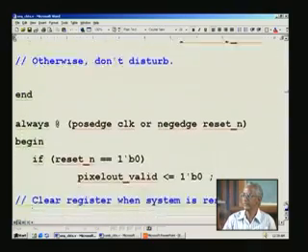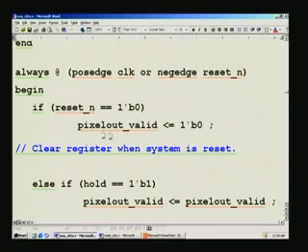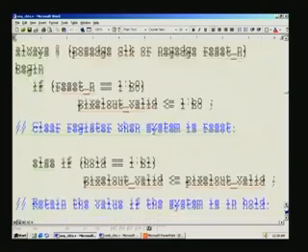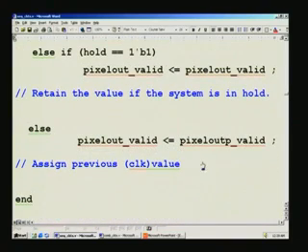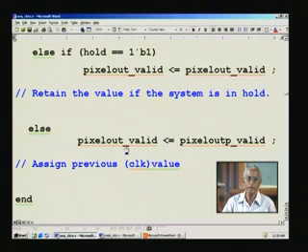And the next register takes this as the input, and precisely reset etc. are the same, hold etc. are the same in this next register. Here that previous content is assigned. So that means, say in the earlier clock this might have matured, it was 1, let us say, that 1 cannot be assigned right at the same clock here, and so what we do is we assign it only at the next clock. That's how you get a 1 clock delay.